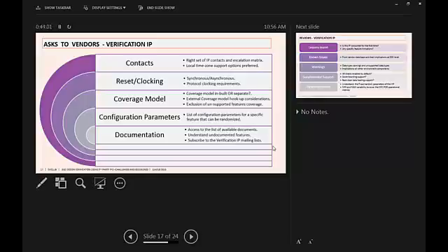The second challenge on the coverage model is that since they treat it as an IP, there will be lakhs of bins, which may not be required for our SoC simulation. So you can go ahead and ask them whether there is any way to disable those. Otherwise, we may need to manually remove them, or they have to manually remove them. Because they treat that VAP as an IP, there will be lakhs of bins, but we may not require them. We may record 100 or thousands of bins, which is more than enough for us.